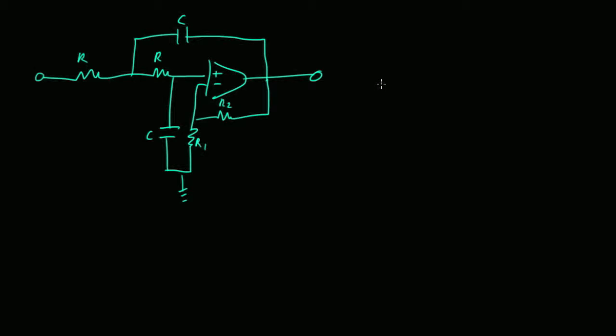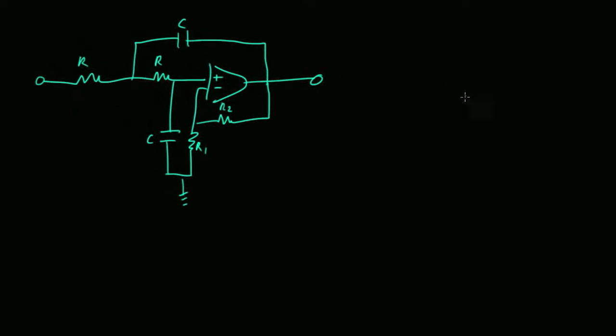If you think about your pole-zero diagram, two poles right here are very, very heavily damped. That's zeta pretty close to 1, which means a gain pretty close to 0. Then you start increasing your gain, keeping omega naught the same.